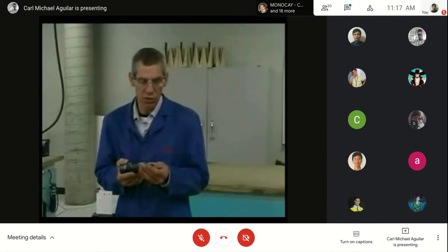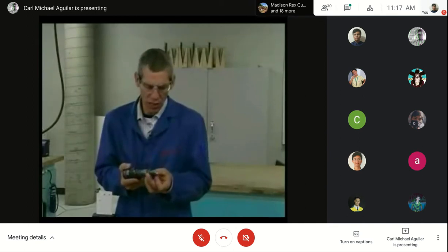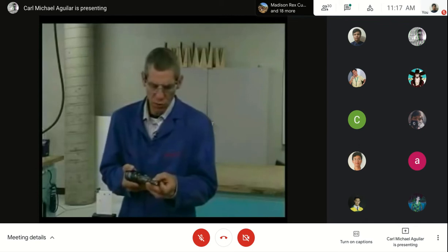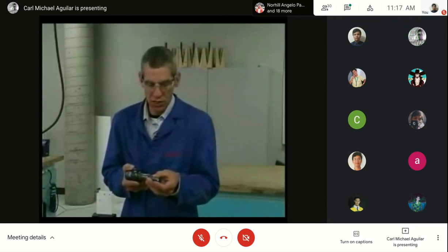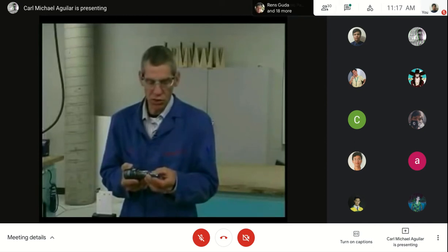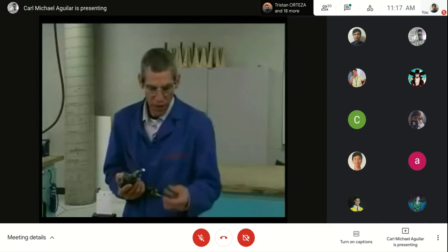So it's a 5/32 rivet with a universal head style. So I'm going to be using a universal head snap that has a 470 written on it, and it'll either say 4705 for 5/32, or it'll say 470 and have a 5/32, indicating that it is a correct snap to use for a 5/32 rivet.